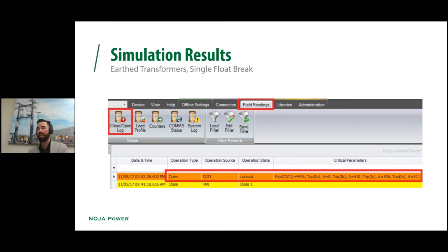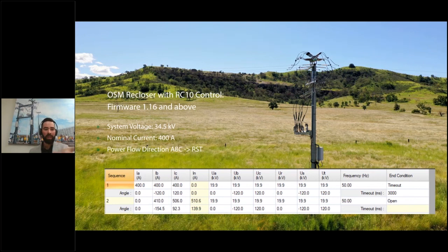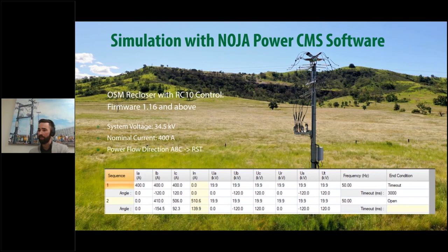And again, had you set this at 20 amps, at 20% I2 and I1, you would have caught this. But if it's a 400 amp network and suddenly you've gone up to 506 amps, that's not necessarily going to get caught with your overcurrent. So you can see that, and you would then be able to pick up that fault condition as being a phase discontinuity.